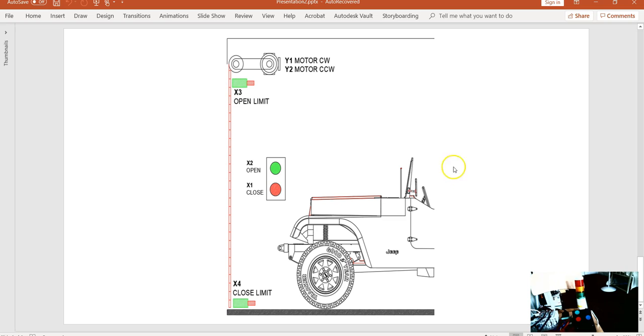I think we'll have counter circuits, so we can actually count the number of cycles that it goes fully open and fully closed. So when it goes all the way open and then all the way closed, we'll count that as 1 cycle. So we'll have timers in there. We'll have counters. We'll probably use data registers to control how fast or how slow it goes up and down.